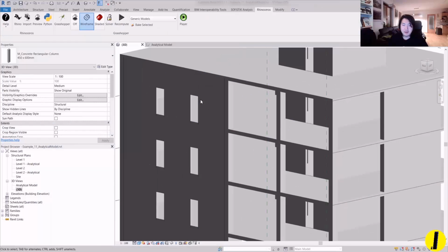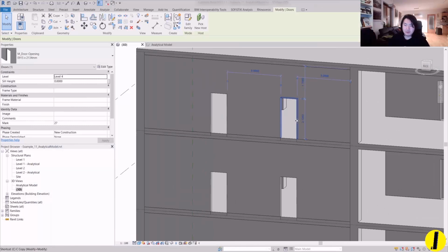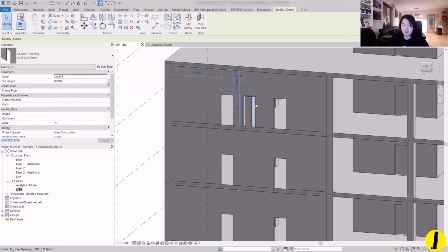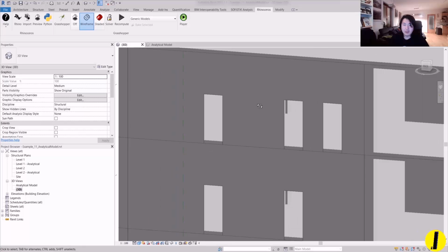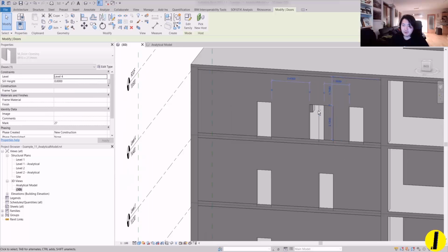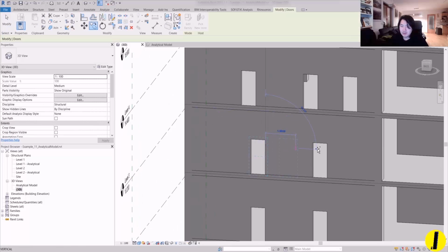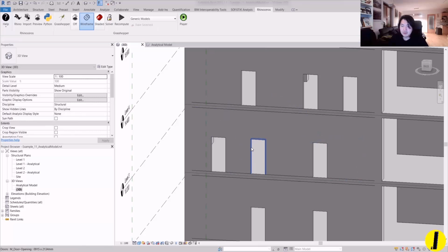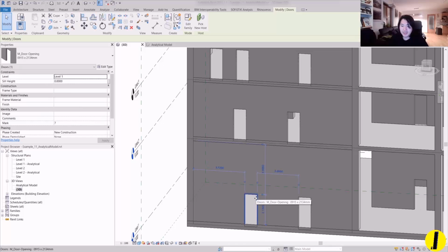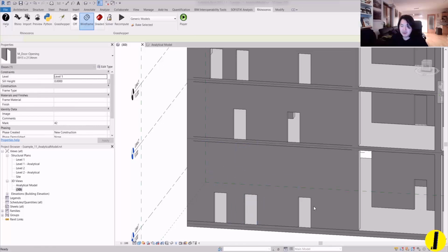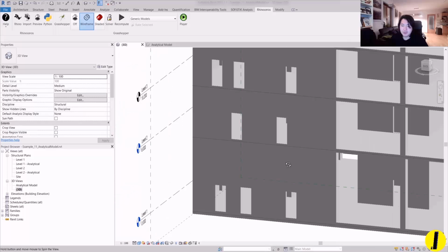So I'm going to minimize. Imagine you may have another door, or maybe some irregular pattern of openings. So I move here, and let's move this window door here, in another position. Maybe I'll copy here in another position, move it a bit, and let's just randomize. Of course, everything we can do now with Rhino Inside parametrically, but for now I'm just doing it manually how I want it.